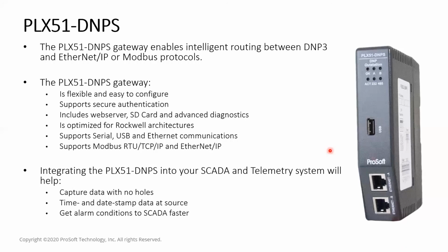So here's another question that's come in, and that asks that if I have two SCADA masters at the top end, can the DNP3 S gateway communicate to both? So the answer to that is yes. What you would need is actually the SCADA master that would go and talk to the gateway requesting the information. But as a slave gateway, it will initiate the unsolicited message to the primary SCADA master.